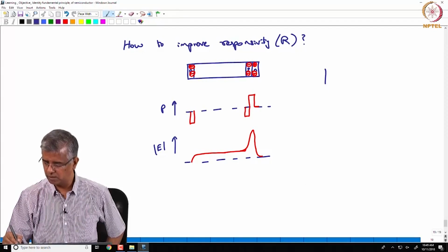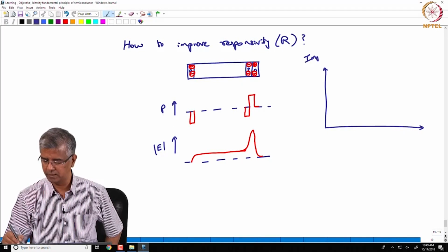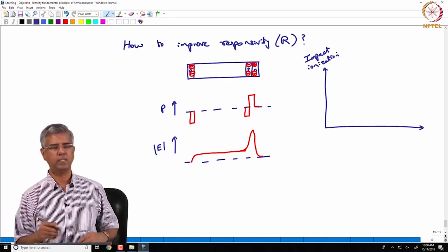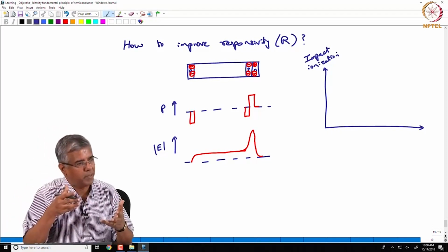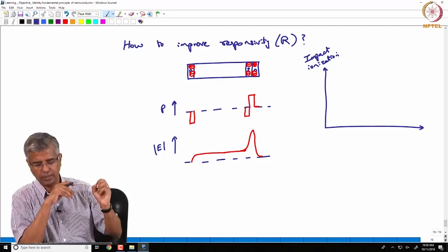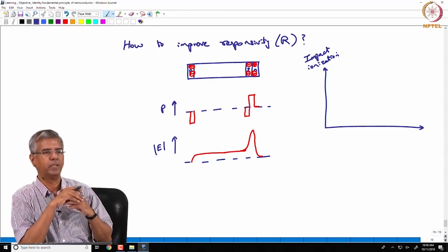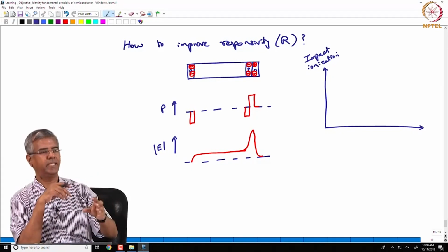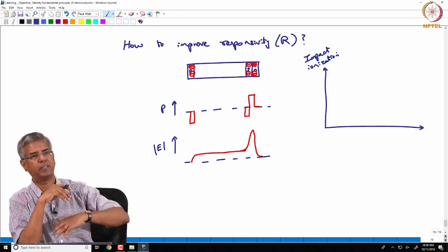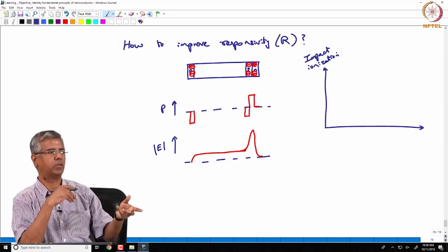Under those conditions, you have a process that's called impact ionization. Basically, these charges have so much momentum, they are traveling at so high a velocity, that if they collide with any other nearby atom, they are going to just hit it and ionize that atom. So they are going to immediately have an electron pop off from that location, and you generate an electron hole pair.